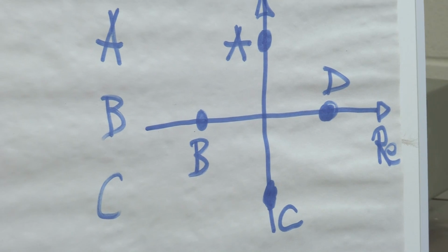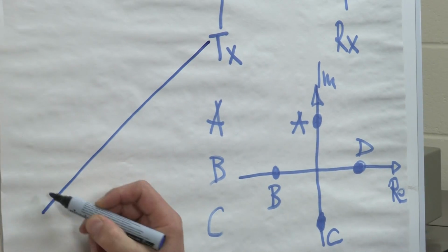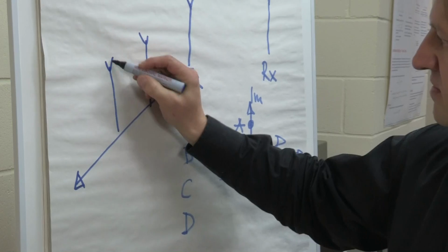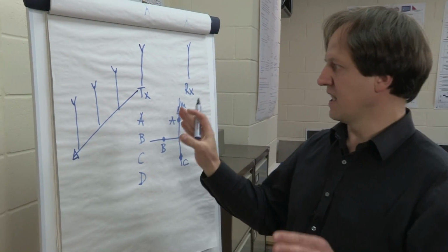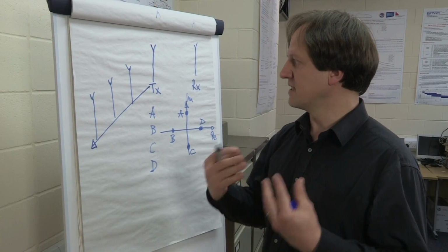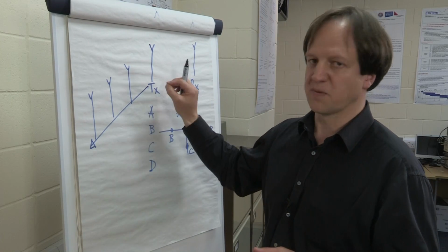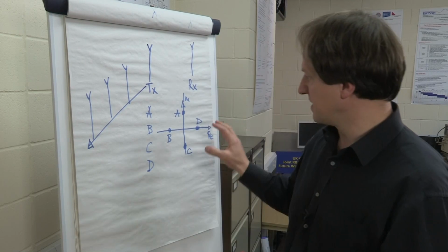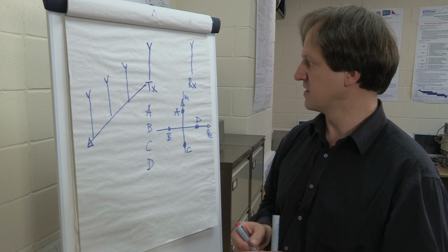So let's assume we have multiple antennas available at the transmitter. So we have a second antenna, a third one, and a fourth one. These antennas have unique positions on that antenna array, and let's exploit that fact in defining the location as a spatial constellation point. So like we have defined signal constellation points, we have defined spatial constellation points now.